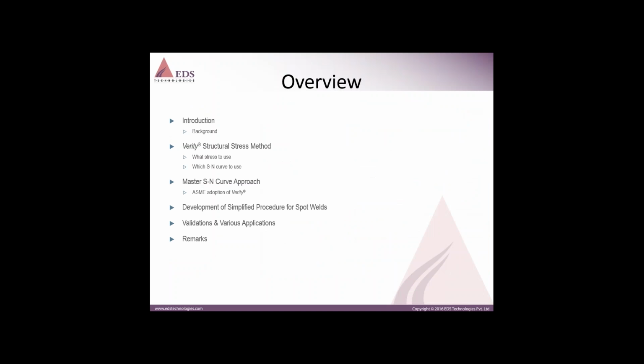Here is an outline. We will start with the introduction and background. Then I will take the VERITY structural stress method, where we will learn what stress, and which stress, we need to take for the fatigue analysis, and which S-N curve we need to consider, and so on. Afterwards we will study in brief the master S-N curve approach. Then we will also see the development of a simplified procedure for spot welds.